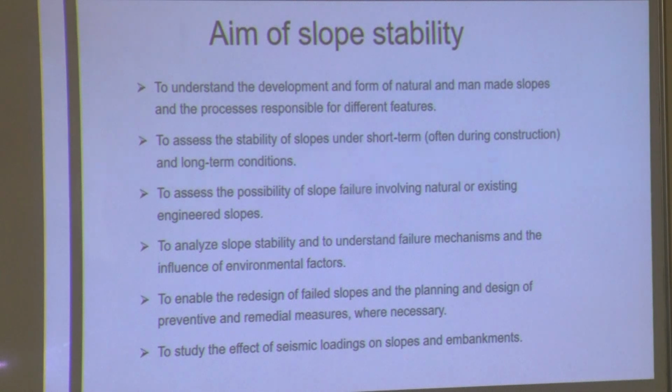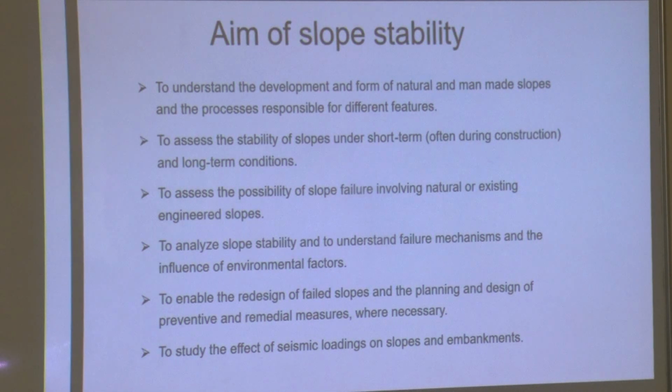So second, it depends on the purpose, depends on the time period for which we will rely on that slope. Particularly in mining, 10, 15, 20, 25 years maximum. 25 years is the maximum lifetime of the rock slope in a mine bench, and subsequently for a tailings pond embankment as well as a waste overburden dam. After that, no one will care about it because they will leave it. But consider, this is the condition outside: you have to rehabilitate all the places as they were before the mining period.